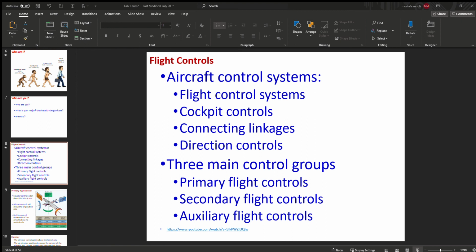We also have the trailing edge flap, we have the plain flaps, we have the split flaps that essentially stick to the trailing edge when they are closed, but they split from the trailing edge when they are not closed. We have the slotted flaps that move in position. We have the Fowler flap and a combination of the slotted and Fowler flap. The difference between these two is that the Fowler flaps essentially move back and forth, but the slotted flaps rotate around this axis. Okay, so you can have a combination of the two as well.